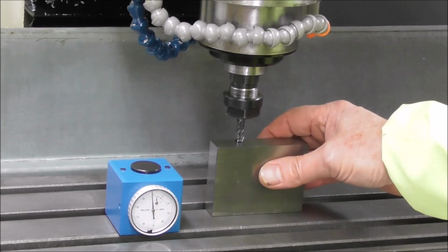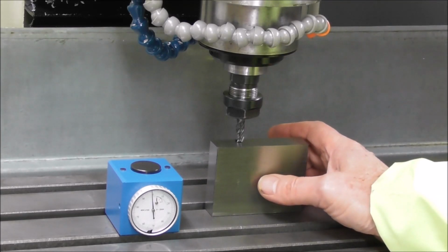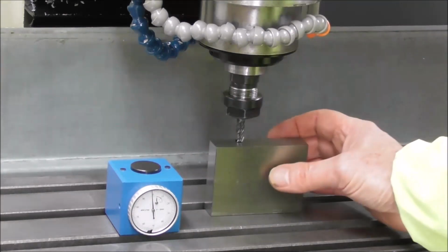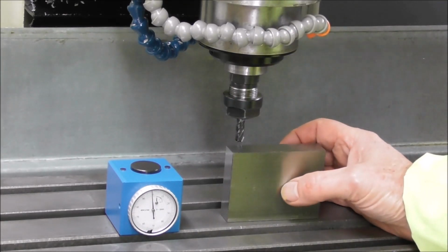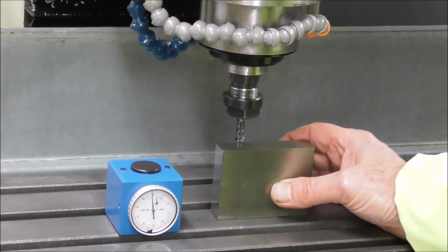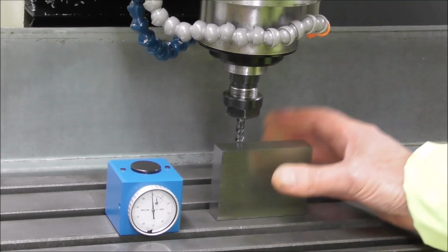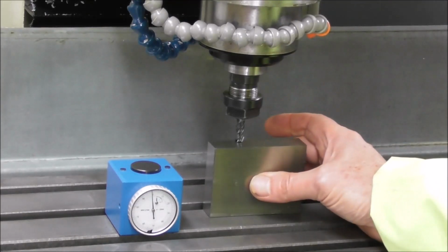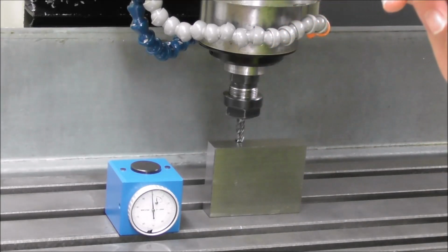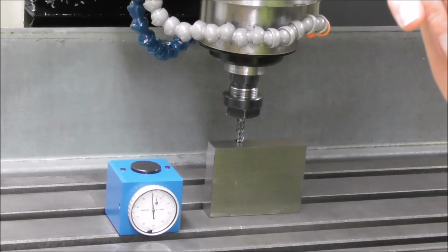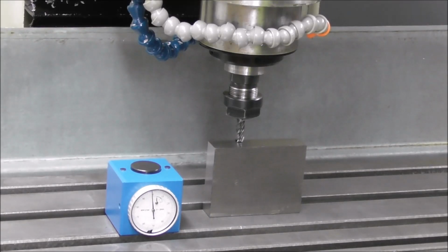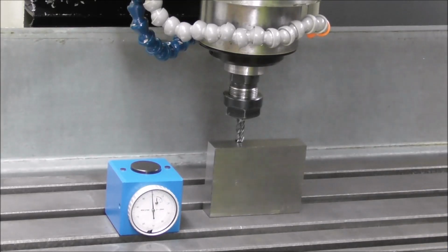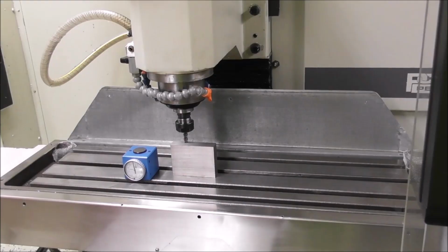So there's probably a bit of luck involved in that, because I set it really quickly while I was making the video, but it completes the circle and shows the system works, and also shows you how you can set your tool heights just with a block of steel or a rolling dowel underneath. As you lift it up in steps until it just enters, then you can push your tool height for that particular tool and it will load it into the software. So that's the 5th method, which is also practical for certain types of work.